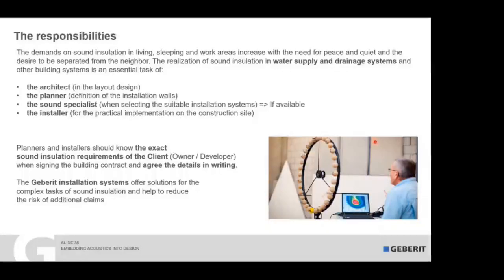Therefore, it's crucial for us to know the exact sound insulation requirements of the client, mostly the owner or the developer. Maybe he already gives an indication to the architect or to the planner, and this should be done in a written way. A dB level, dBA level should be agreed, maybe even a standard should be agreed on which you want to build up the building. Because, as I said, this will be our first question. When you have an acoustic requirement, we will ask you first, okay, what level would you like to achieve? Is it 30, 35 dBA, whatsoever? Which standard are you going to use? And then, of course, we can also give you good support.